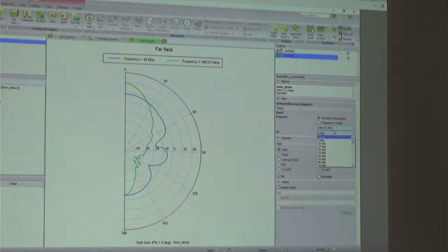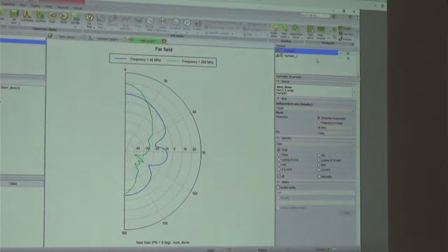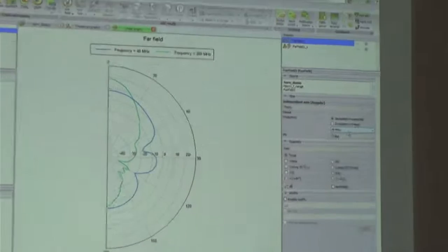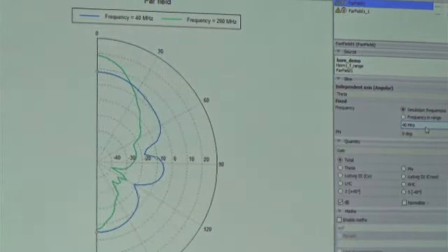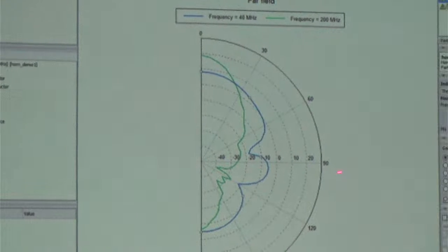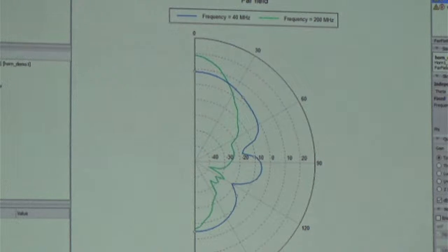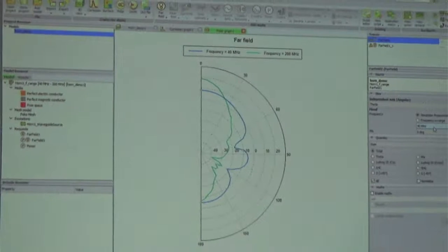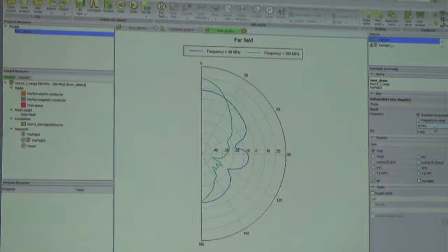And you can see the higher you go, the more structures you start getting in your primary beam. And maybe the other one I can go to 40 just to contrast it. So it is 40. This is just a 1D slice. And here again, what we are plotting is basically the gain of the antenna. I'll come to what that is, but it's a representative of your angular distribution of your field of view, like when you transmit something from here, how it's going to be distributed.